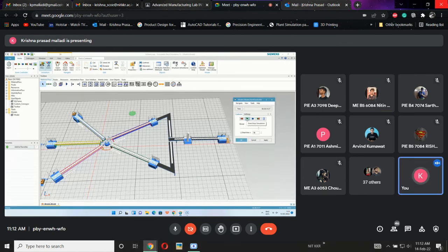Based upon the part which you are using, we can choose the type of conveyor. If the material is smoother in nature, then we need to use a belt conveyor. If the material is harder, then we need to use roller conveyors. Based upon the part, we need to define what type of conveyor to use. If the material movement is high, if I'm using 1000 parts per hour or 10,000 components per day, then I need to consider wear and tear also. By considering those things, I need to find what type of conveyor is preferable for the layout.